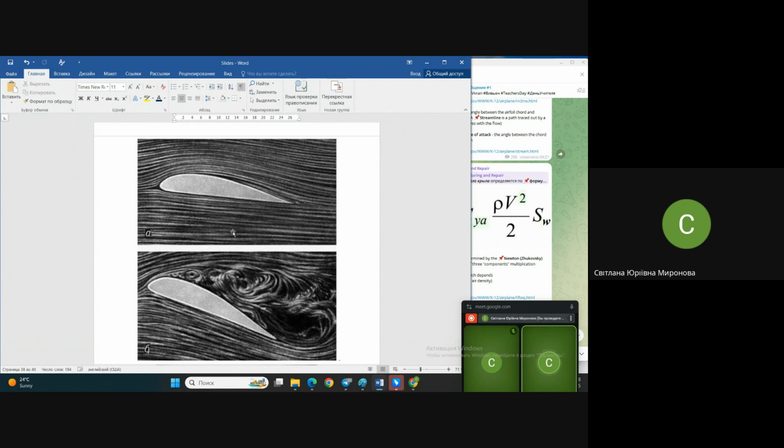I hope you understand that piece of flap changes angle of attack, and angle of attack is an important characteristic because it may result in such flow separation, at least partially on the flap, and instead of working for our benefit, instead of increasing lift, flap may reduce lift.